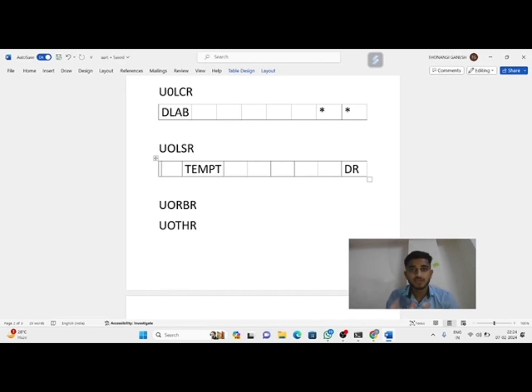Whenever we want to transmit data, we give that value, which is stored in a temporary buffer, and then it is transmitted to the receiver device. Whenever we give 8 bits of data, it is stored in a temporary buffer. While transferring bit by bit from LSB to MSB, when the last bit is transmitted, the whole buffer becomes empty. At that time this TEMT bit becomes 1; until then its default value is 0. The buffer being empty means our transmission is completed.